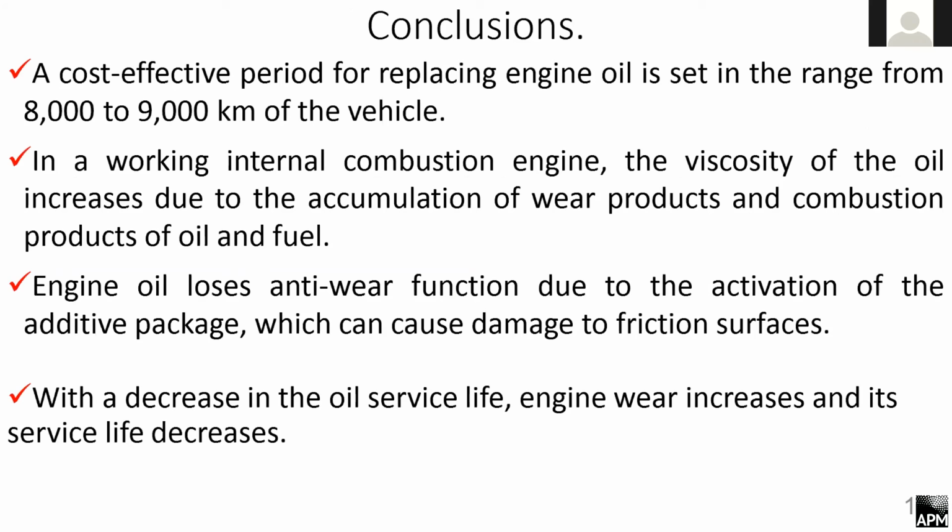The following conclusions were made. A cost-effective period for replacing engine oil is set in the range of 8,000 to 9,000 kilometers of the vehicle. In a working internal combustion engine, the viscosity of the oil increases due to the accumulation of wear products and combustion products of oil and fuel. Engine oil loses its anti-wear function due to the depletion of the additive package, which can cause damage to friction surfaces. With a decrease in the oil service life, engine wear increases and its service life decreases.